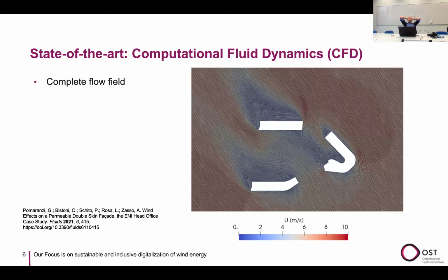So obviously the other way is, well, let's try to do the computational fluid dynamics way. Let's try to run some simulation and see what happens. The advantage is you get a complete flow field everywhere. The problem is, I don't think anyone here did CFD practically, but the main problem is, to give you an idea, to model a 10 centimeter by 10 centimeter grill, you need around 50 million cells.